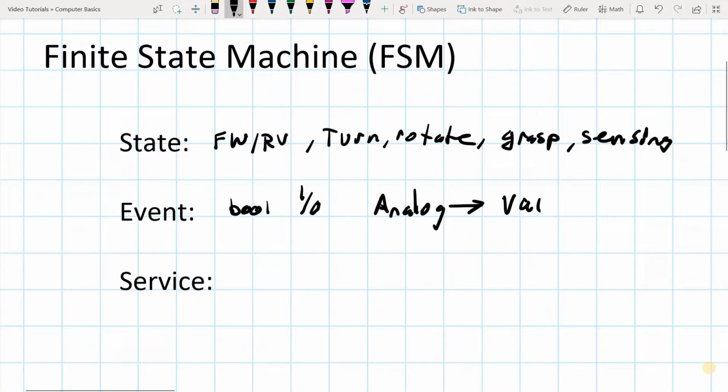So either one, these two things can be written as a conditional statement. Like if the state of something changes, that's either true or false, then you could write an if statement about it, or you could say something like, if the IR sensor value is less than some distance, right? And then it will either be true or false. So this is kind of this Boolean effect, where it's either true or false. One loop, your analog sensor is below the set value. The next loop, it's either at or above the set value, and now you want to perform some action.